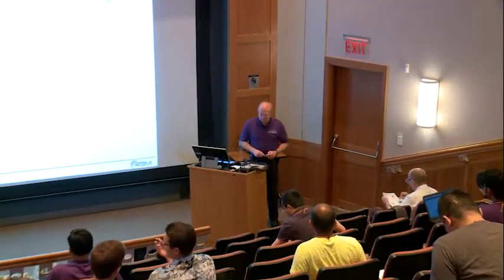To wake you up and start with, I would like to repeat some important aspects we have discussed yesterday in the context of phosphor thermometry. As I explained, phosphor materials are ceramic, and these ceramic hosts are doped with metals, transition metals, for example, like europium. As we have seen, there are many different choices. So they're doped by ions, which are then the materials that actually show a certain sensitivity with respect to temperature.